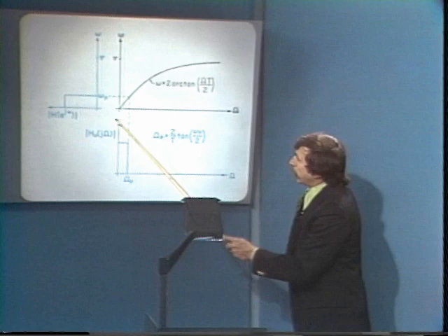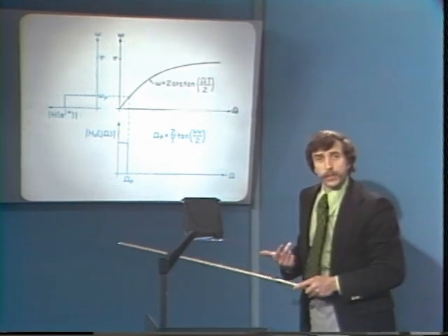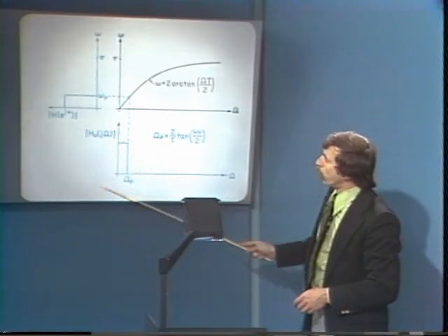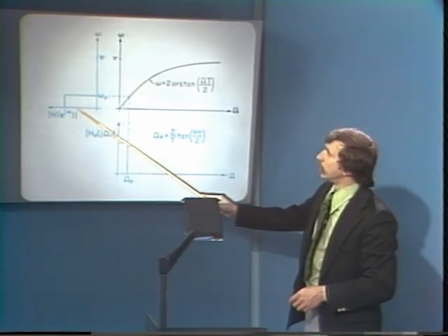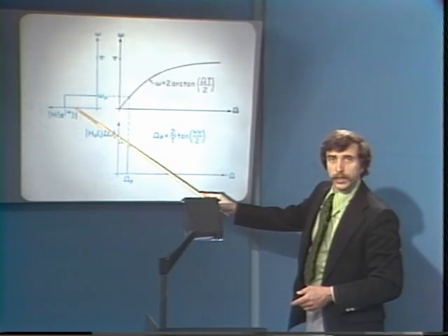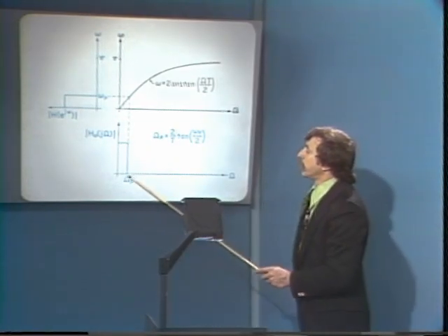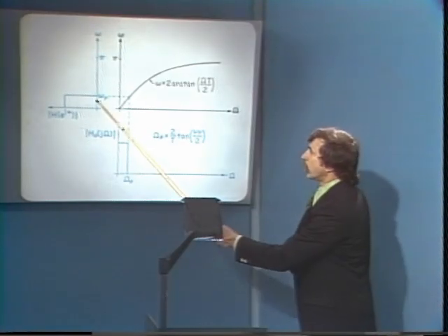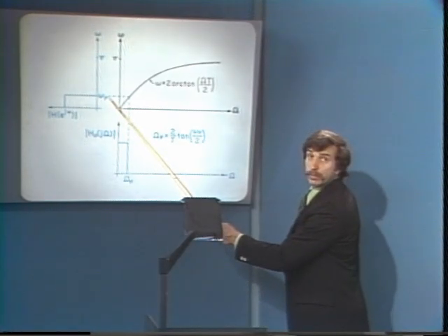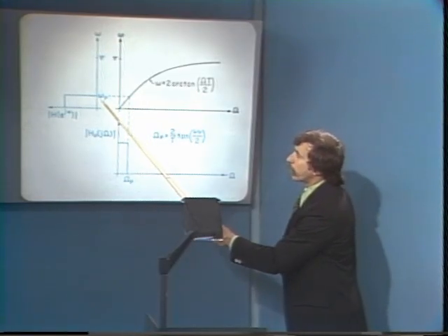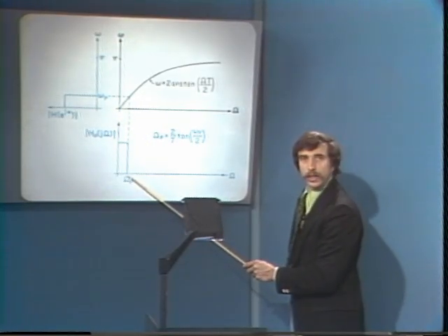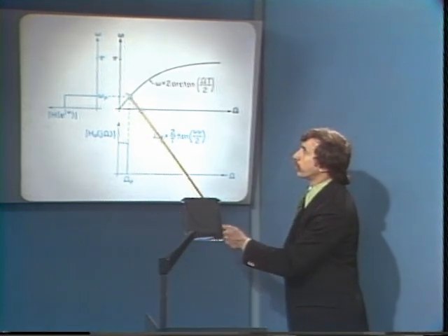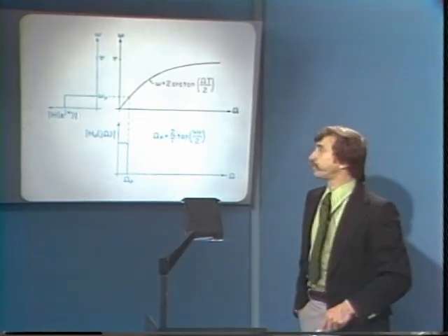Now, one of the things that says is that for the filter design, if we wanted to design an ideal digital filter, an ideal digital low-pass filter, then to decide on the specifications for the ideal analog filter, we would simply pre-warp, what's called pre-warping, the cutoff frequency to an analog cutoff frequency, which would get unraveled back to the right cutoff frequency when we go through the bilinear transformation.